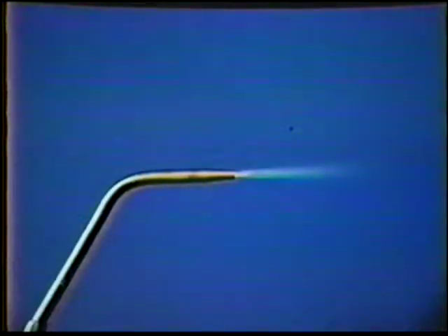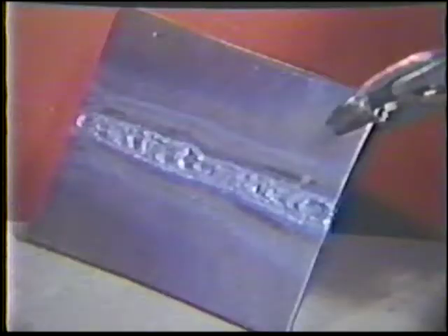Fuel gases must be mixed properly. Too much oxygen for the acetylene flow produces an uneven weld bead when welding steel. There will be no sign of the even ripple found in most quality welds. Gouging may occur along the bead edges. The excess oxygen makes the flame too hot and can cause excessive melt-through.